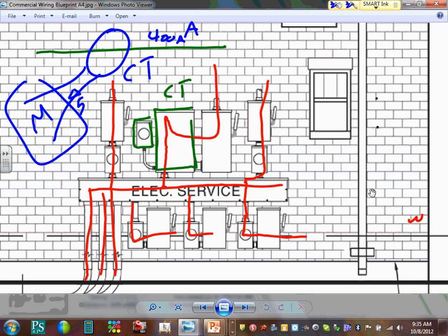Can somebody tell me, if I have a 200 amp here, what do you think this will go to proportionally? 2.5 amps. So whatever goes through the cable will reflect through the meter, right? That's what a CT is. More amps in, more amps in the CT out, but the max goes to 5 amps. That's why they start with the max, 400 to 5.